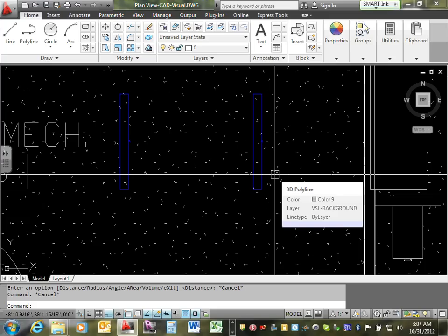Zoom into here, grab this corner, and now try to go out the bottom. Shift scale it. Very good. Now zoom all again, and let's go first line. Okay, now let's see. Go back to the... Oh, you click on this, and yeah, let's go change your units. Enter. Change this decimal into architectural, and okay. Hit OK again. Just OK. Yep, that's fine. And then just grab it and measure. See if it gives you feet now.